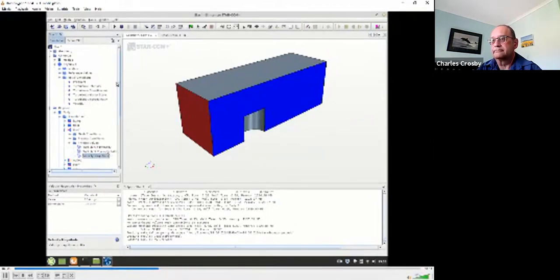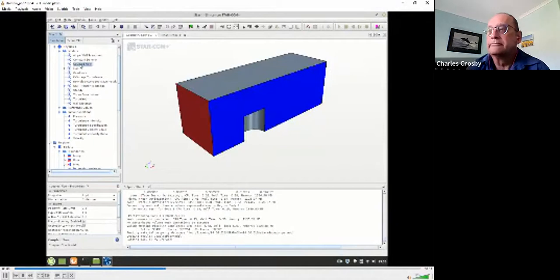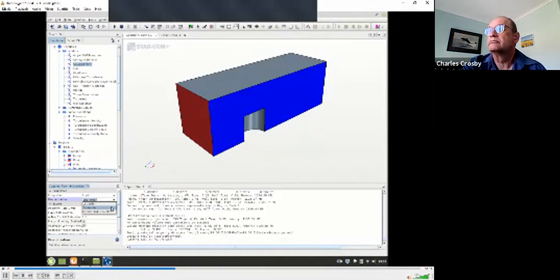So it's worth taking a look at our physics models, where we've got our coupled flow solver, and we are using second order discretization for the convection terms. Remember what we did in Fluent, we could set first order and second order for better precision or more stability. We'll run the second order.